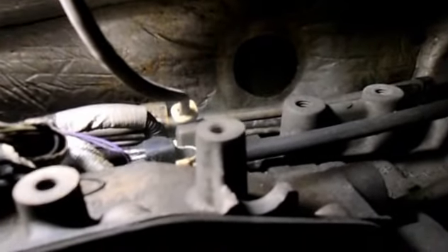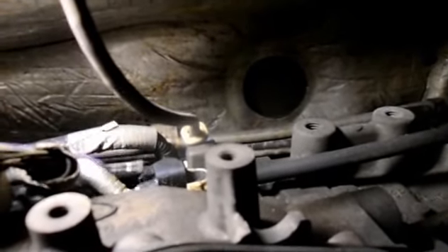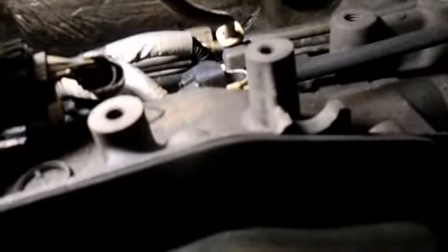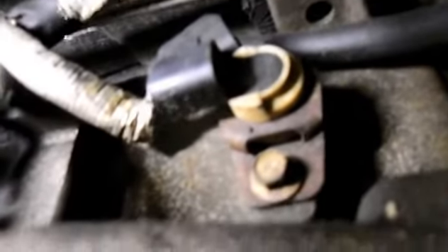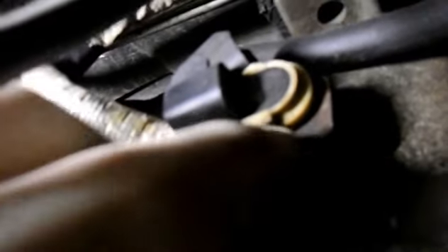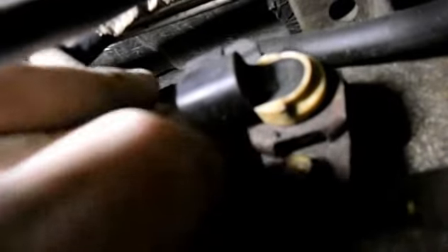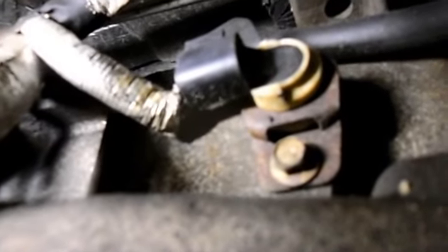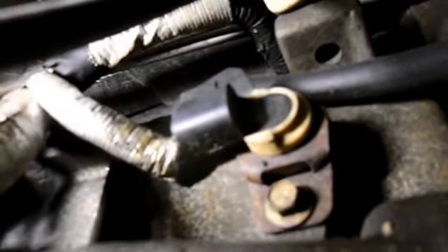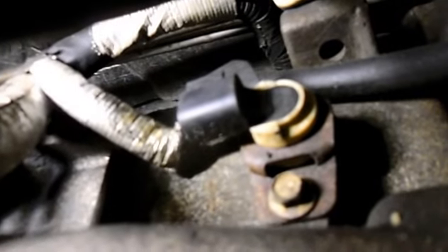What we're going to do is, these wires we could take off again. We're not going to need these. We're just going to pull them off. And then, let me see if I get my camera up there. Sorry about that. Right on the side there, you see this little 10mm bolt? We're going to take that 10mm bolt out, and we're going to pull this sensor out of the truck. So let me grab a 10mm ratchet, and we're going to remove that sensor. Come right back. Let me get some tools.